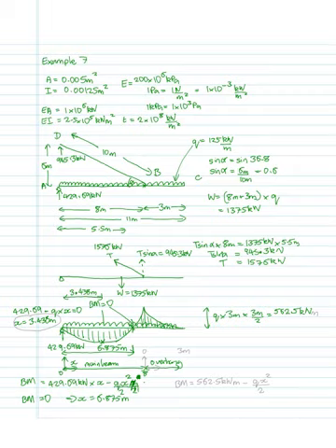So we've set up some geometry for the problem. Now, if we wanted to get the equation for this bit here of the overhang, so again we would set up another system later on, starting from x is equal to 0 up to x is equal to 3 meters, to represent the overhang, and the equation for that one, the bending moment, is going to be equal to this 562.5 kilonewton meters.